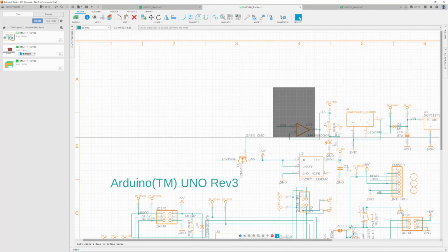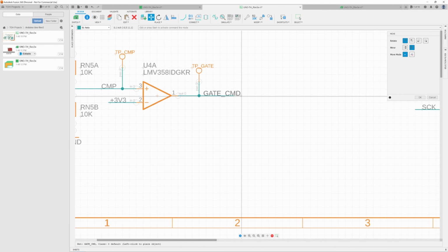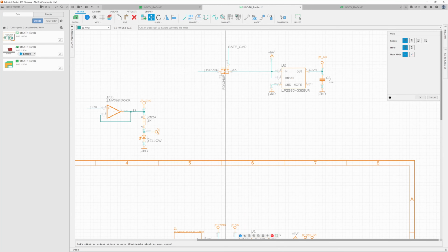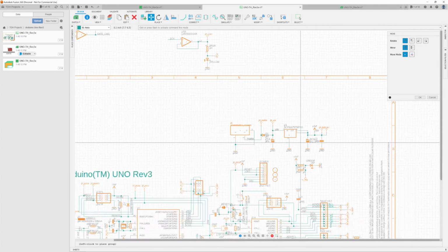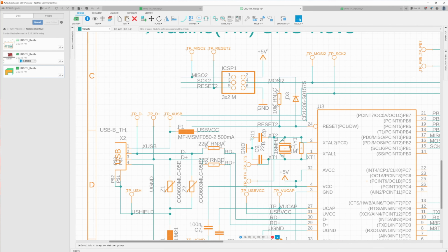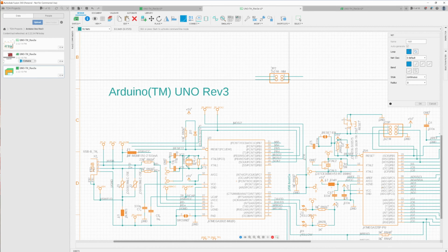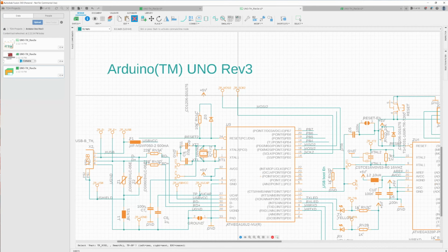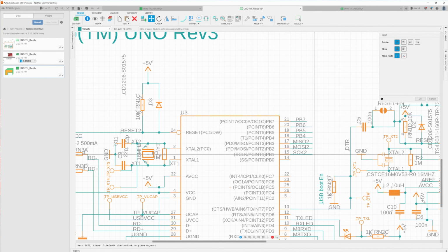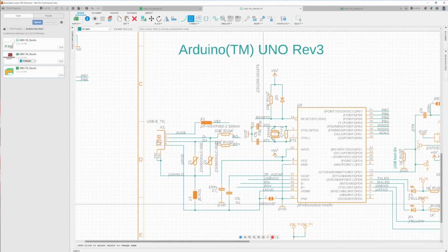The process of editing the schematic takes long, and it does not serve the purpose of this video. While I explain the strategy I'm following here, the editing will play in high speed. There are some things I don't like in this schematic. Long nets going around, labels out of grid and not symmetrical looking. Schematic functional blocks like regulators, microcontroller interface, supply inputs are messed up and there is no clear separation between them.